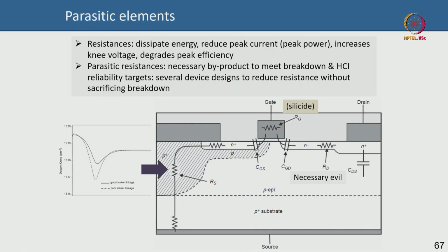Okay, so over to the whiteboard here. What you see here is basically a schematic of the LDMOS device with representative parasitic components that are listed out. So gate resistance is a significant parasitic resistance, and polysilicon gate is not the best, that is why people use silicide also on top of that, which I already discussed. CGD, the gate to drain coupling capacitance, CGS, the gate to source coupling capacitance, these are extremely important parameters. This is a necessary evil, the drift region blocks the voltage, the VBR actually drops here, it is a 2-dimensional profile, but anyways the gate drain spacing largely determines the breakdown voltage.